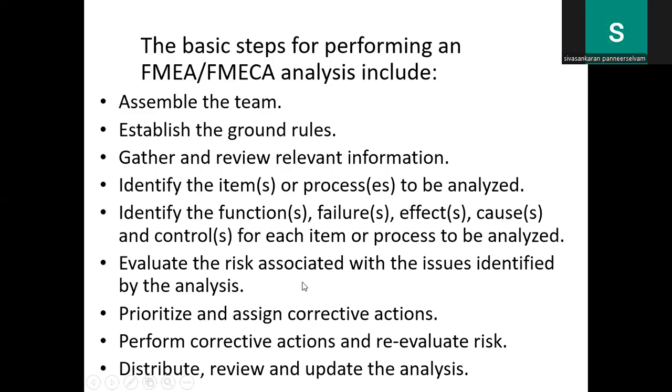And what are the procedure guidelines to be followed in every industry by implementing failure mode effect and criticality analysis? The first point is calling together all the different working teams from various departments, and we need to identify strong goals by establishing proper ground rules and collect various field information and review them properly, identify the different areas of interest by proper analysis, and collect the different failure modes for possible root causes for each item of assembly in